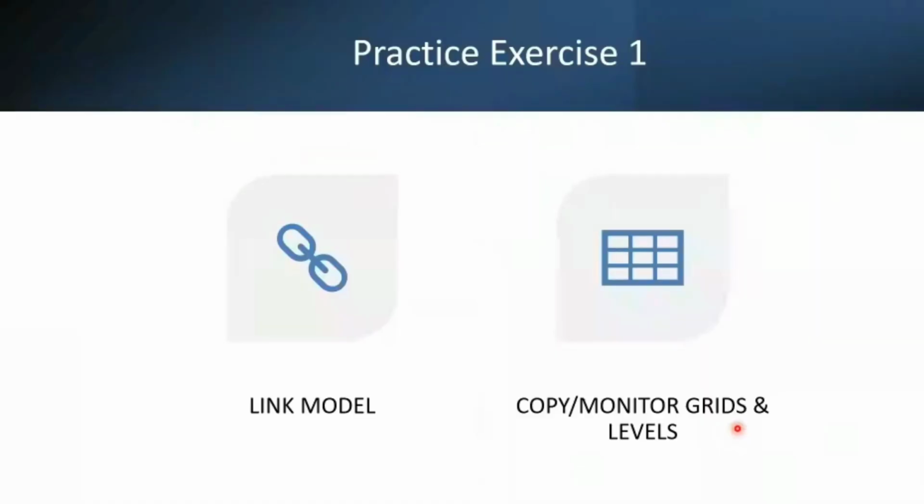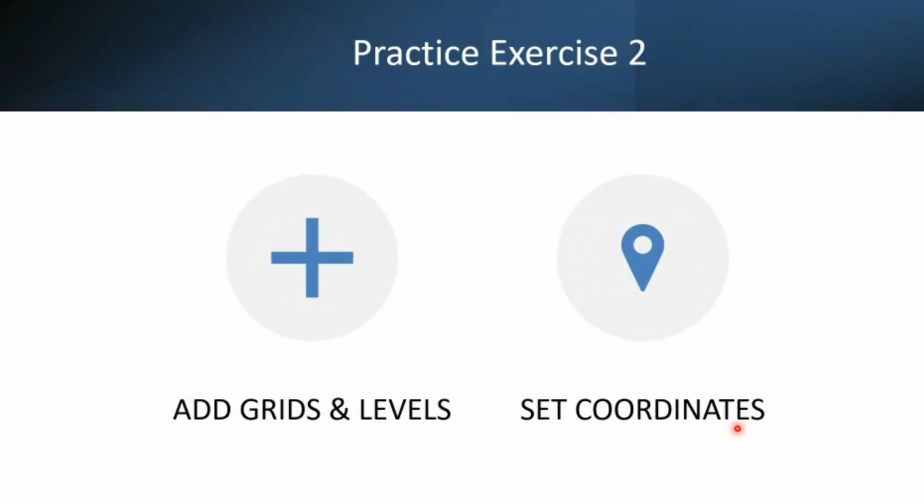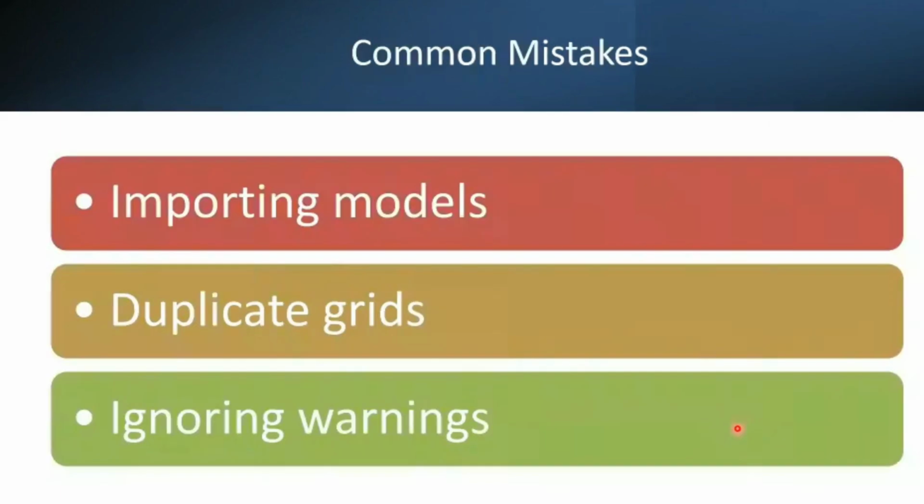And we will do 2 exercises for this tutorial. The first one is linking a model, and the second one is copying and monitoring grids and levels. And in the second exercise, we'll talk about how to add grids and levels and how to set up coordinates.